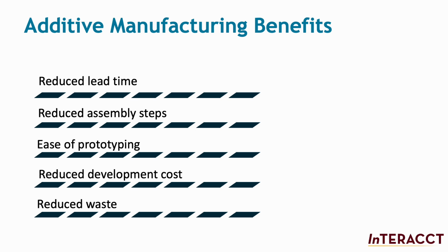Additive manufacturing facilitates the consolidation of components and reduces the number of steps to production, especially for early phases of the design and prototyping stages. Reducing the number of components also reduces the time and labor needed to make the part, resulting in reduced developmental costs. Additive manufacturing reduces the amount of waste because products are built layer by layer and unused feedstock materials can be reclaimed and reused.